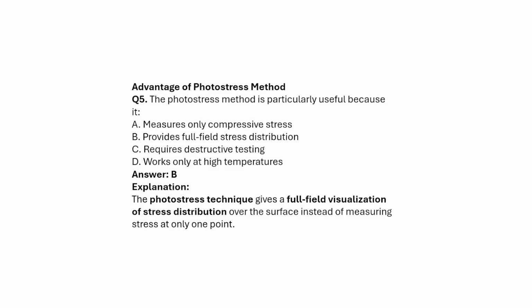So the major advantage is that it provides full-field stress distribution. Answer B. Okay. The photostress technique gives a full-field visualization of the stress distribution over the surface instead of measuring stresses at only one point.